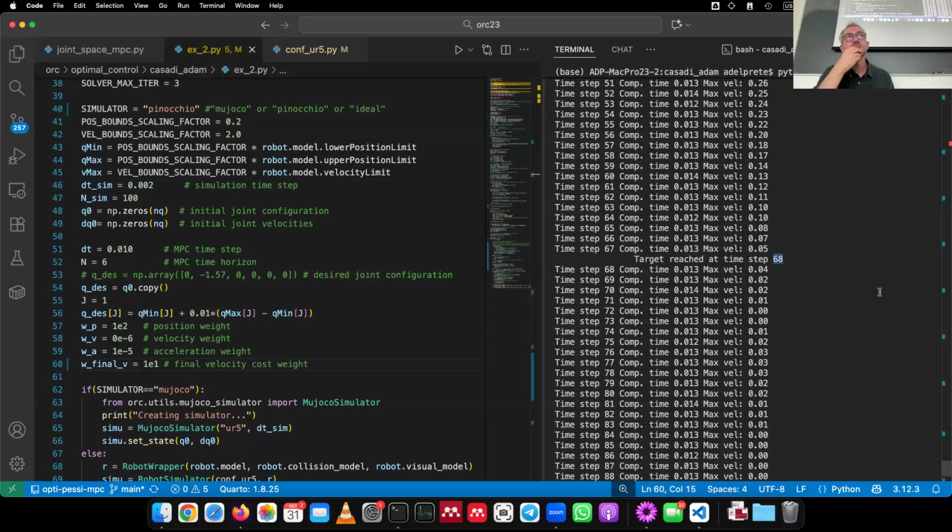Start an optimization. I set up a nonlinear problem where the final state must be equal to the initial state. I set the cost function to 1 maybe, and then I hope it finds something. Yeah, you just set up a classic trajectory optimization problem, and you simply add a constraint that the terminal state should be equal to the initial state. That's it.